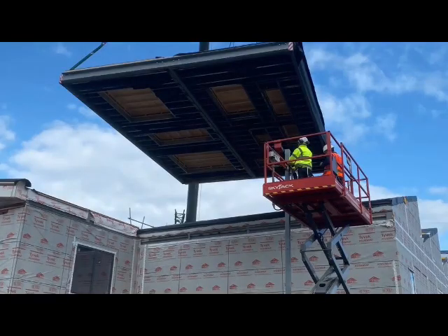So next is the roof installation. How do we install panel roofs? Panel roof is not like other roofs that you just install and then you use your nail to hit it inside. Most modular building constructions are usually steel structures. So how do we actually install our roof? We make use of a self-tap screw and then a machine to fasten it to the steel structure.